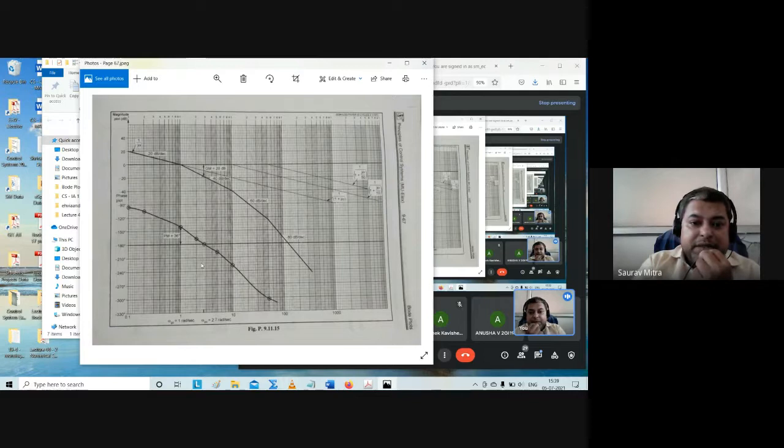And at omega pc 2.7 radian per second, which is somewhere here, okay, at this frequency 2.7 radian per second, you push this up and you find how much is the gain here. So at omega pc 2.7 radian per second, the gain is coming to be almost minus 20 dB. It is not minus 20, it is around minus 18. Okay, but they are saying minus 20, so let us take it. So you can very easily find out graphically the gain at 2.7 radian per second, which is the phase crossover frequency.